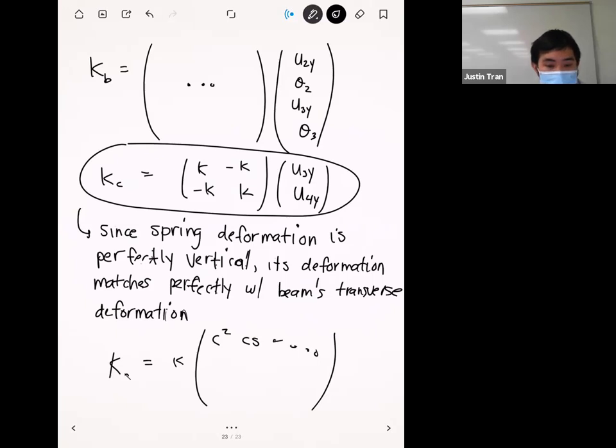All right, question. Is the beam stiffness matrix a constant for all beams, regardless of cross section? I-beams, rectangular, angle bar, etc. No, it's a good question. It would be different for the different kinds of beams, and the way that it would be reflected is in different moments of inertia, right?